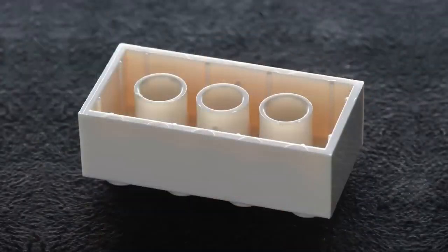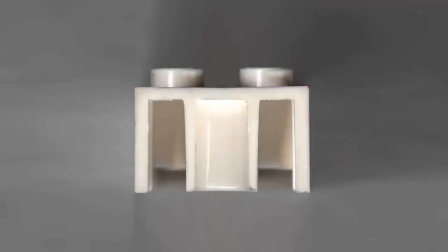On the bottom edge of the brick, you can see ejector pin witness marks. And what's most clever to me is where Lego designs their draft angle. The outside of a Lego brick must be square. So if you cut a Lego brick in half, you can see that these inner supports are thicker at the top than at the bottom. There's a draft angle of about 1.5 degrees. This helps the ejector pins push the brick off the mold.